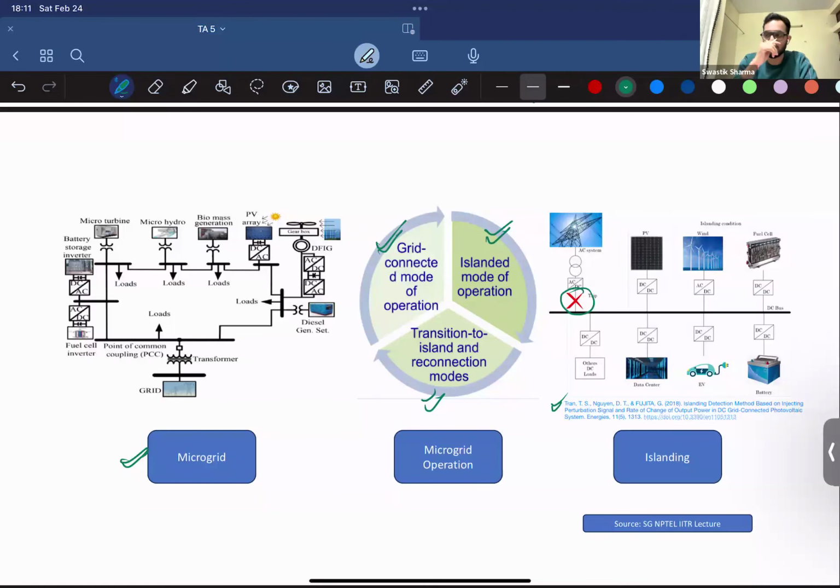So there are three modes. Now, when we have grid connected mode, it's easier for us to manage these resources, right? Because the central controller sits at the central place. But when it's islanded, these are localized to different distribution feeders. So how can we manage them, and how do we know that a microgrid has gone islanded? There can be certain trips that we don't know of, and let's say an islanding happens. We need to be able to detect that an islanding has happened, because until and unless we know, we won't be able to quantify if a microgrid is acting remotely or not.